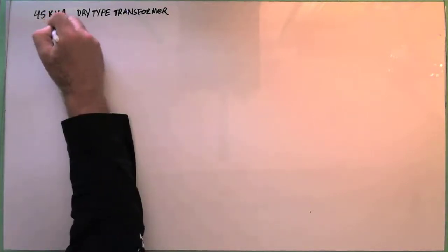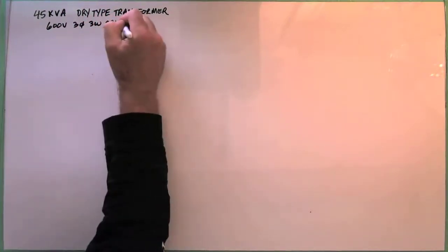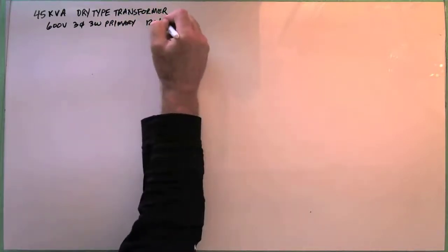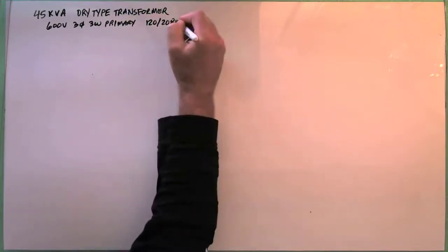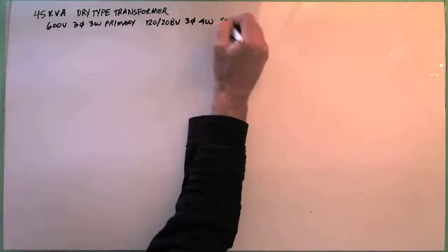And this says it's got a 600 volt, 3-phase, 3-wire primary. And it has a 120/208 volt, 3-phase, 4-wire secondary.